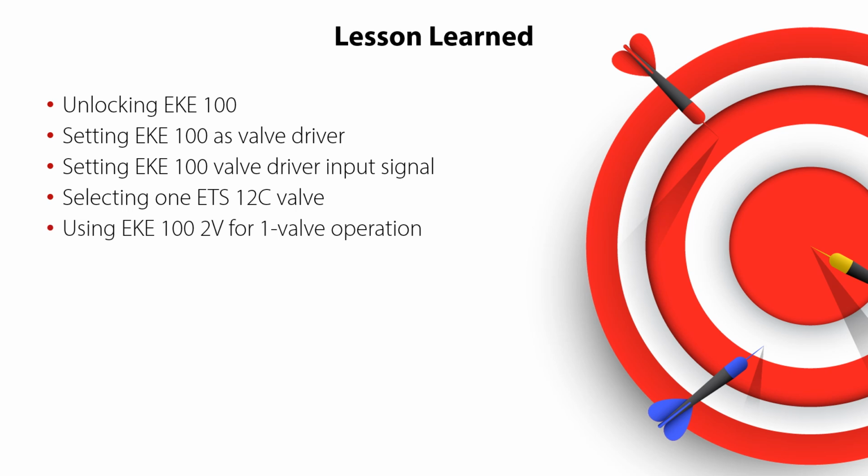You know how to set the EKE 100 2V version for one valve operation only. And finally, you know how to lock the EKE 100 again after completing the setting. All this ensuring a correct and safe system operation.